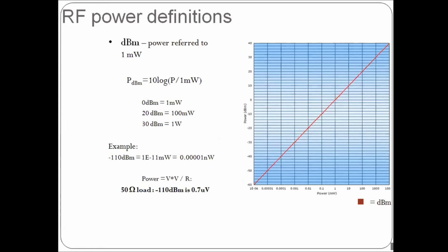Generally, we would say that power measurement is done with the help of dBm. dBm is decibel relative to 1 milliwatt. That is 10 log of the power received with respect to 1 milliwatt of power transmitted. In tower applications and all, the power levels are represented with the help of dBm only. So the transmitted power is considered as 1 milliwatt.